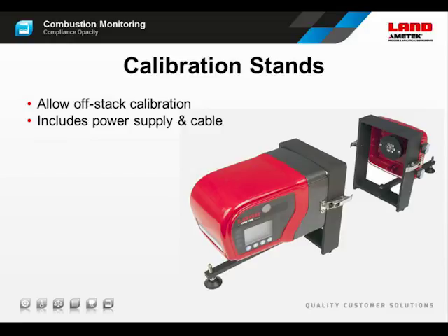And in those cases, there's an additional step that has to be taken. In addition to measuring opacity, that opacity has to be converted to the dust concentration. And the 4500 Mark III can do that calculation. It uses a parameter called the dust gain. But determining the dust gain requires a calibration relative to a reference method measurement, which is quite a complex procedure. And that's not something I'm going to go into in more detail here.